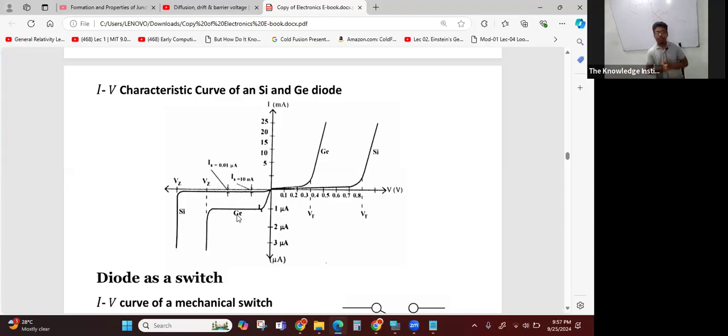So today we discuss the mechanism right after we connect two semiconductor pieces, one p-type and one n-type. If we connect p-type and n-type, what happens right after that? As soon as we connect them, due to the concentration gradient, diffusion occurs. As the diffusion starts, the built-in electric field is created, and due to that there will be a small reverse current. Initially, the diffusion current is maximum and the reverse current is zero.